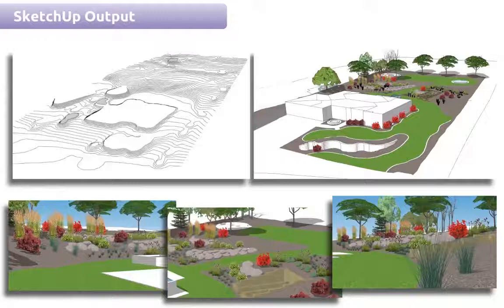And then you'll combine all of those photos in Pix4D and just tell it to run it. You could actually model each individual mission and then merge those in Pix4D, but it's easier to just take all of your photos and put them into the same project file and run it.